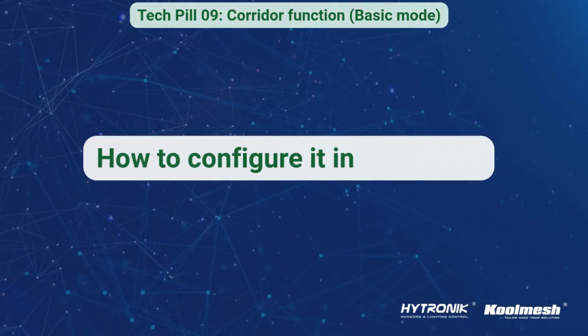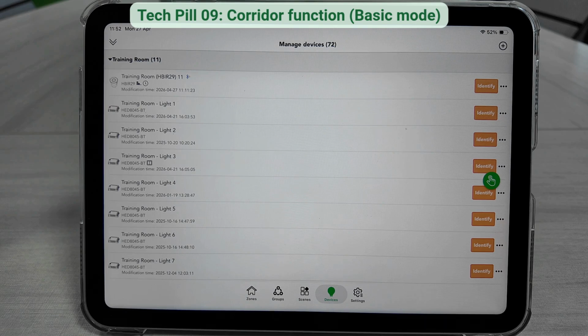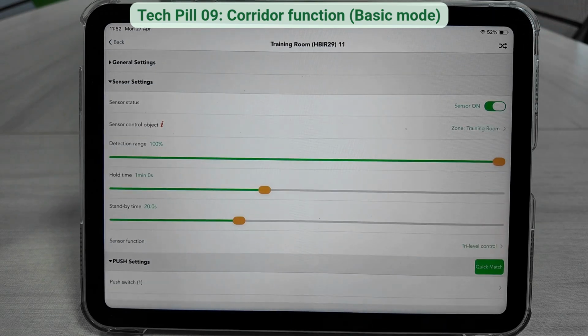Now let's configure it in Koolmesh. We open the device in Basic Mode, where all the main parameters are shown on one screen. In the Sensor Settings section, we enable the sensor and select the control object, in this case, the corridor zone. We can also adjust the sensor sensitivity.